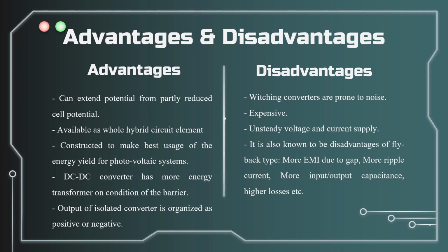Next, for disadvantages, switching converters are prone to noise, expensive, unsteady voltage and current supply. It is also known to be a disadvantage of flyback type. More EMI due to the gap, more ripple current, more input-output capacitance, higher losses.